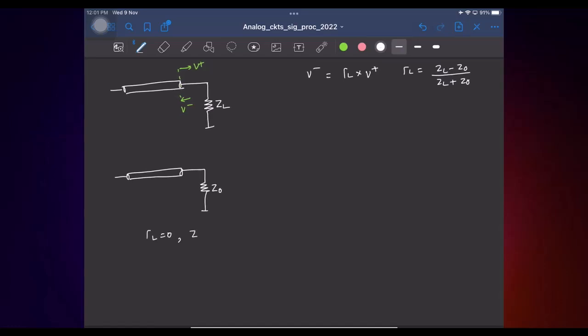And what about the input impedance? That's also Z0, right? And that made sense because the load here is saying that the ratio of the total voltage to the total current must be Z0, and on the line this condition is satisfied only by the forward component, so nothing gets reflected back. So at any point on the line, the total voltage will be only the forward component and the total current will be only the forward current. So the impedance at any point on the line is Z0.